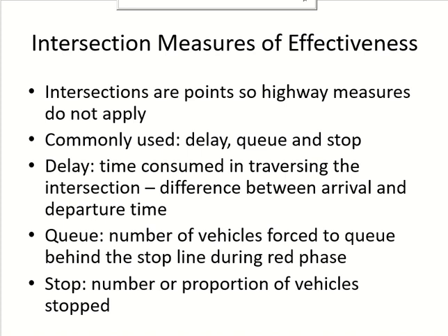Depart meaning you will cross the stop line. So from joining the queue till you cross the stop line, this is counted as your delay. It is the difference between arrival and departure, which could include the time you are spending in the queue. Clear?